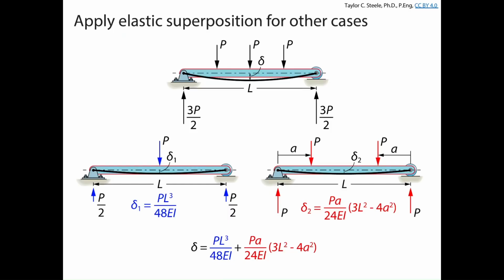We've got a beam with a point load at the middle. And if we break out the loads at the outside, we've got a beam with point loads equally spaced from the support A, right? So I've got a solution for one load, I've got a solution for the other 2 loads, and I add them together. What's that called? Does anyone remember the name of why we can take the results of an elastic analysis for one set of loads, take the results for an elastic analysis for another set of loads, and add them together? What is that called? Does anyone remember?